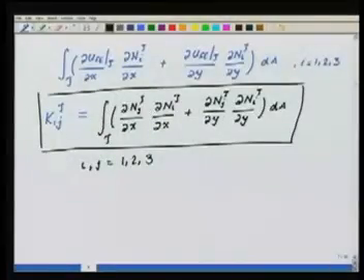Everything that we are doing is exactly the way we had done it for the 1D case. The only thing is that the number of entries increases. Here we are dealing with partial derivatives of the quantities of interest. If I have to do this for the standard model problem that we had taken, the generalized one, then we will have to do it with the A11, A12 and A22 sitting there. So the stiffness matrix entries for the element can now be computed in terms of the derivatives of the element shape functions Ni and Nj, where Ni and Nj have been obtained from the interpolation that we have done earlier.